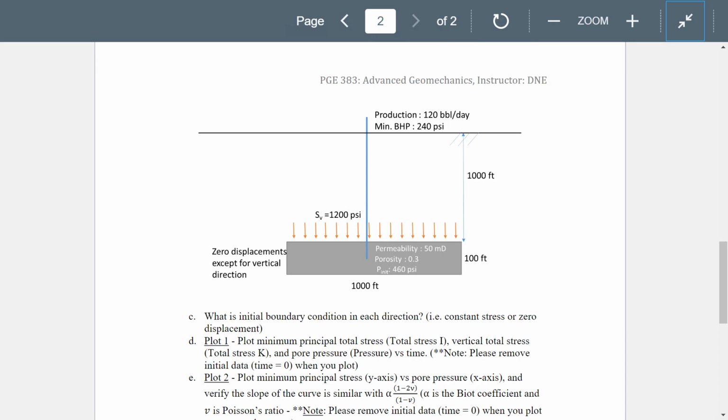And you're going to have to compare these simple analytical solutions, considering that pore pressure changes everywhere the same, that it's an infinitely long reservoir, with an actual model that you're going to have to build using this reservoir simulator called CMG, in order to match the analytical solution with the numerical solution, and see how pore pressure affects that change of horizontal stress.